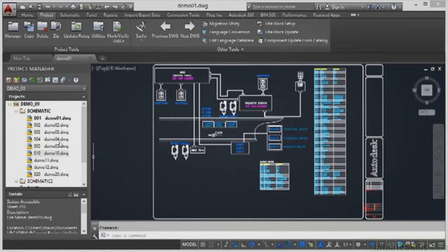Now we're just using default numbers and default file names here. They're not exactly descriptive, but if you think about how this works with your project manager in AutoCAD Electrical, you can define all of these drawing names and sheet numbers very, very effectively so that someone can navigate the drawing and the project almost seamlessly. So the drawing and the project can be related to each other. Obviously that project would have a different project name, and the drawings would obviously have different names as well. And it would all relate to each other in a naming philosophy that everybody's familiar with. So that's how you change your drawing list display configuration in your drawing list in Project Manager in AutoCAD Electrical.